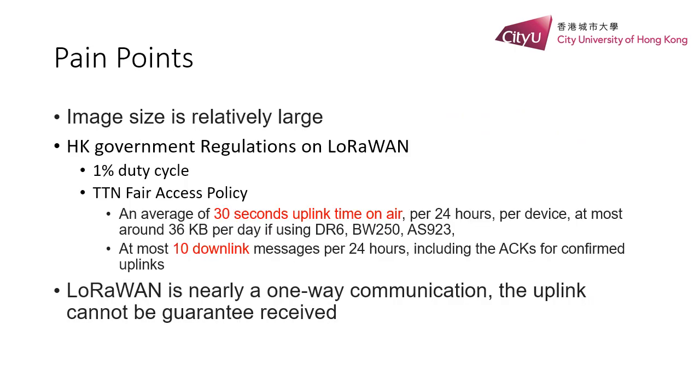As a low data rate technology, sending image data is a pain point. Besides, for LoRaWAN, the local governments have regulations on it. For example, in Hong Kong, it requires 1% duty cycle and need obey the TDM fair access policy. TTN stands for The Things Network, which is a global open LoRaWAN network service provider. They provide cloud LoRaWAN service. As the organization contributes to the LoRaWAN community a lot to make LoRaWAN fair use to public.